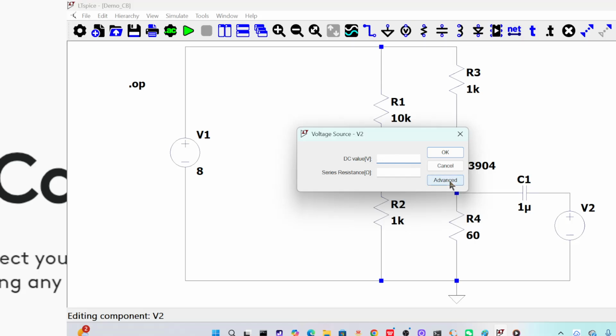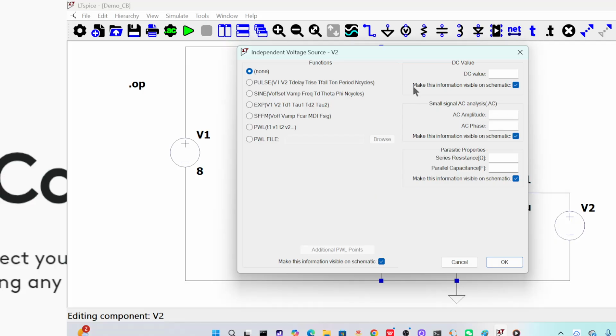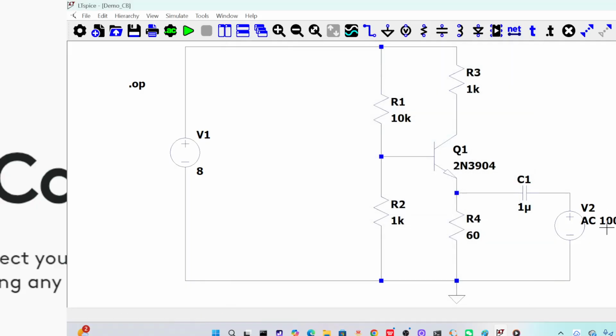You need to tap around here to access this menu. In this menu, there are many options. The one that you need is specific to small signal analysis. It is small signal AC analysis, and the voltage that you need is probably 100 micro. 100 micro is quite okay. And the output is normally tapped in here. So I will just use, and then we tap here.